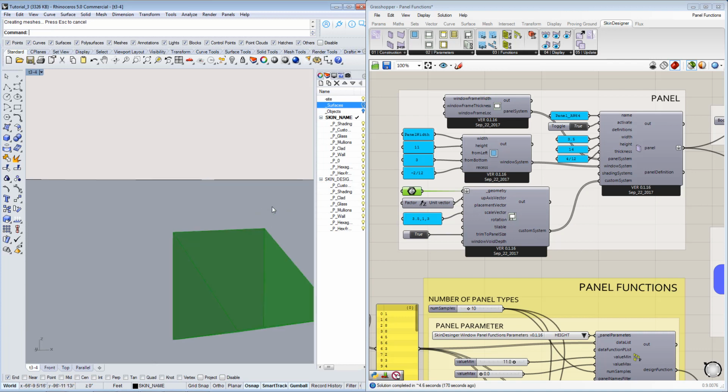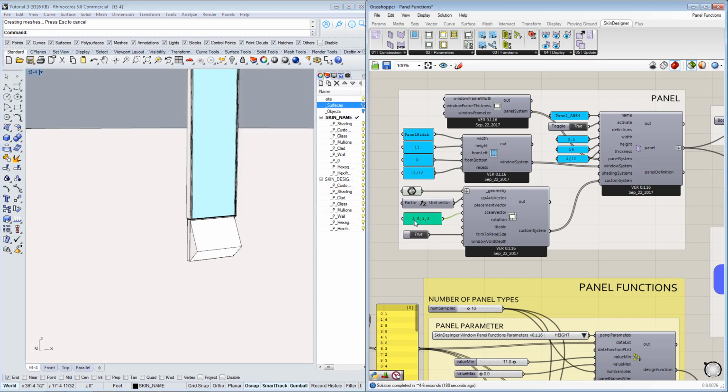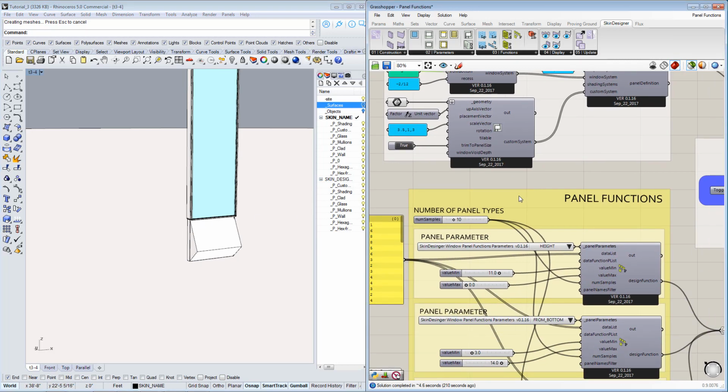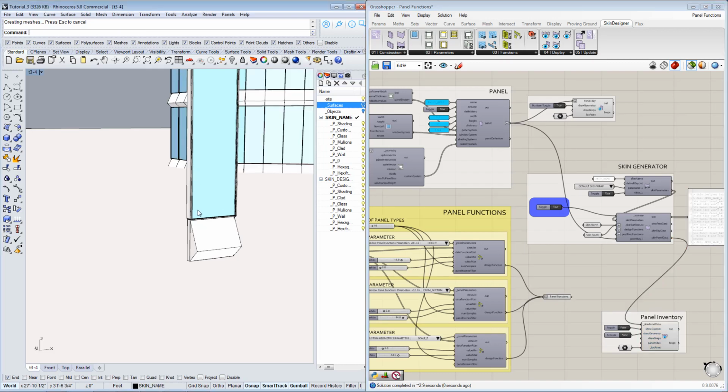It's a triangular shape. It's 1 foot by 1 foot by 1 foot in every dimension, which allows us to scale this up or down. In this case it's matching with the x axis, the 3.5 scale, to the panel width. It stays at 1 foot on the y-axis, and is scaled up 3 feet on the z-axis to match that distance from the bottom of the panel to the window start, right? We can just run this first, and then we can see the extent of this facade, then describe what we're doing with the panel functions.